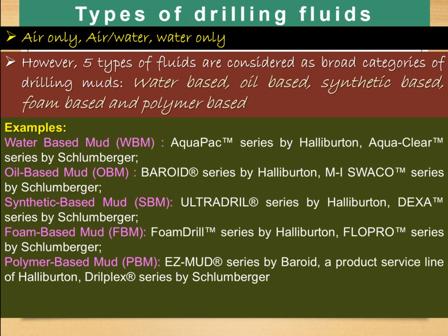Drilling muds and drilling fluids are the same thing, but the overall material needs to be understood. Only air can also act as a drilling mud or drilling fluid. An air-water mixture, often called foam, is also used as a drilling fluid. Water only also. Now, as and when required, other things are mixed along with these additives. Okay, so water-based, oil-based, synthetic-based, foam-based, and polymer-based are the 5 main fundamental types.